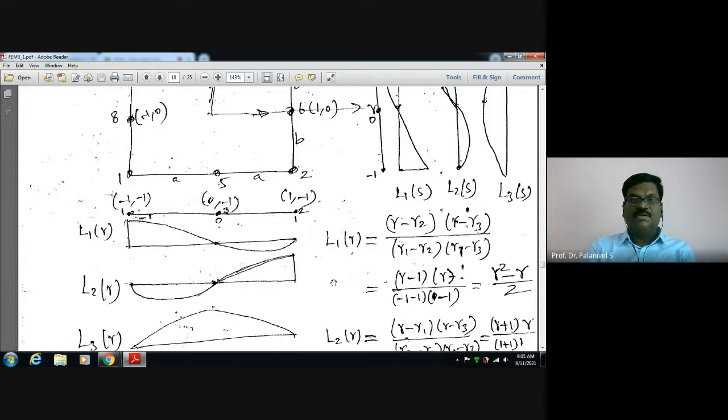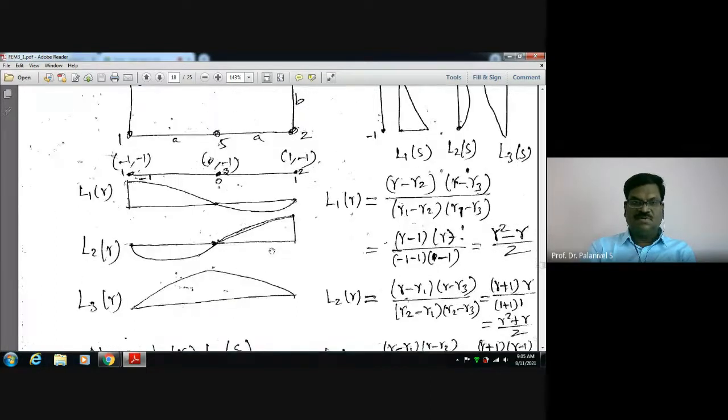In order to get a shape function for this rectangular element, what we have done, we followed the superposing technique. These shape functions of the one-dimensional line element, the R and S direction, are called fundamental polynomials. By superposing them, we can obtain the shape functions for nodes 1, 2, 3. All this I showed you, how to superimpose.